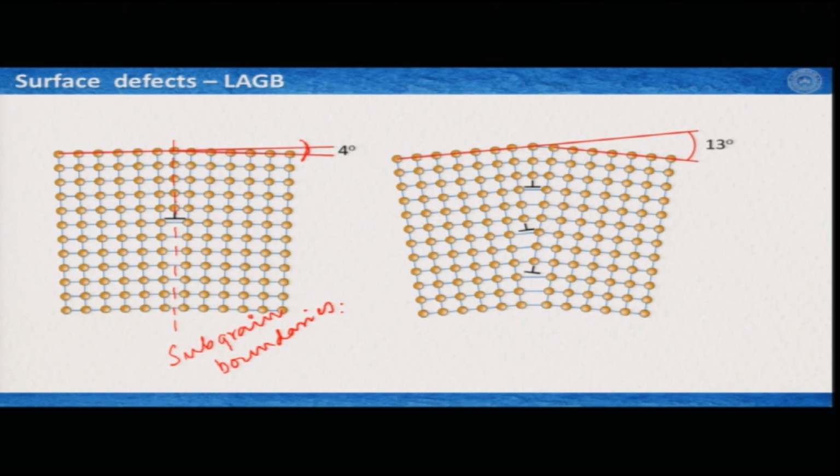Where the angle between the two grains is very, very small. And here this is also a subgrain boundary with higher grain boundary angles. And what is important is that this could probably be your grain boundary. What is important is that these grain boundaries are marked by dislocations, and if we have dislocations at the grain boundaries, that means the grain boundaries are also a storage, a place where you can find more and more dislocations.